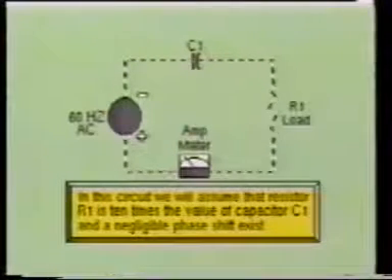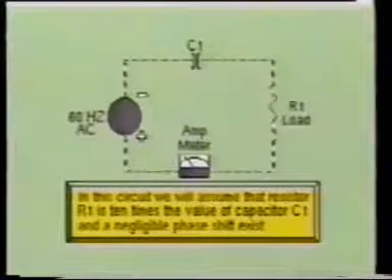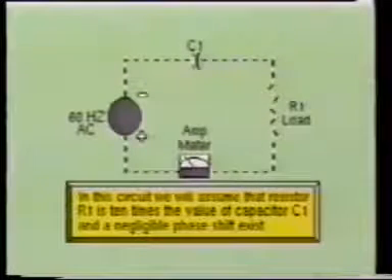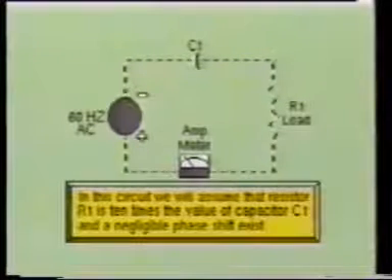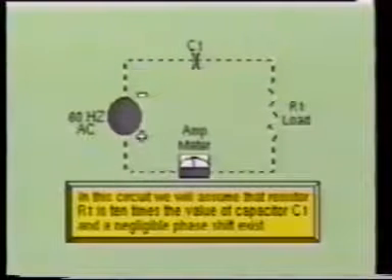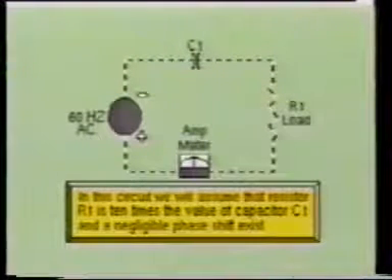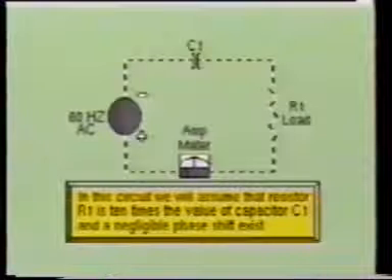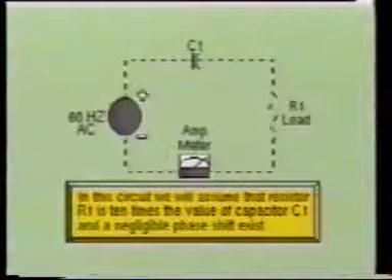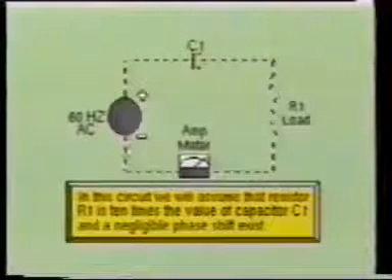Next, the sine wave starts in the negative direction toward its most negative peak value. As it does, the amp meter starts to swing to the negative reading, indicating a current flow in the opposite direction. The capacitor will also be charging in this direction. After the sine wave has reached its most negative peak value and the capacitor has become charged, the sine wave starts back toward the zero reference line to start the process all over again. As the AC sine wave continues to alternate first in one direction and then in the other, the capacitor will continually charge and discharge through the load of the circuit.